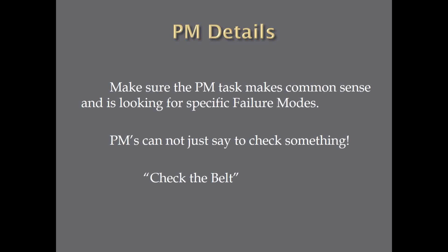It says make sure your PM test has common sense. What specific failure modes are you looking for? You know, what if your PM says check the belts? What does that mean? It might mean something to somebody that's been in maintenance or been around the plant for 20 years. What does it mean to a brand new maintenance person that's out there when he has a PM that says check the belt? Well, is he just looking to see if it's inside the guard?